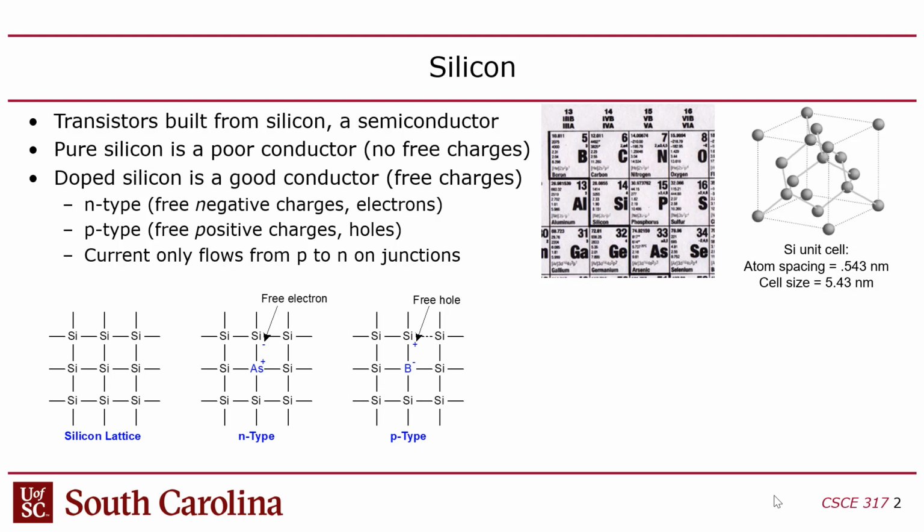But if you hold up 2 ends of a wire with a large enough voltage potential between them and start moving them closer and closer, eventually there'll be an arc of electricity that goes across. And what that arc really is, is the air ionizing between the 2 conductors. That ionized pathway of air, that's the electrical arc, is the charge carriers, which is what allows the electricity to flow.